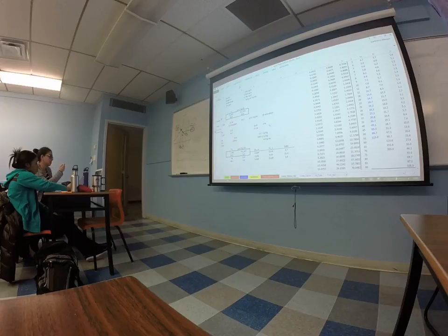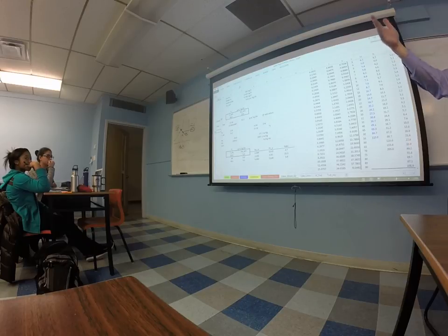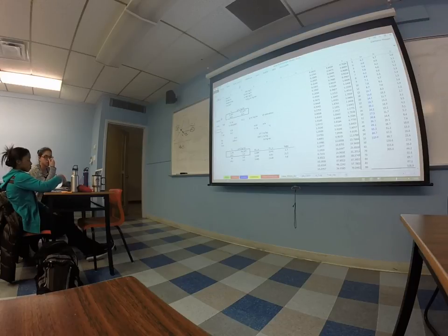And the higher you go, the more this will be different, because your CPs are going to be more and more away from those typical values that you find in those tables. Those values are used a lot by people who do ventilation in buildings and stuff like that. The type of air that we use in ventilation is in a very narrow temperature range, so you can use those values, no problem. But in drying, especially, and in things like cement industries, you go to even higher temperatures. Then you really need to use the functions at those higher temperatures.